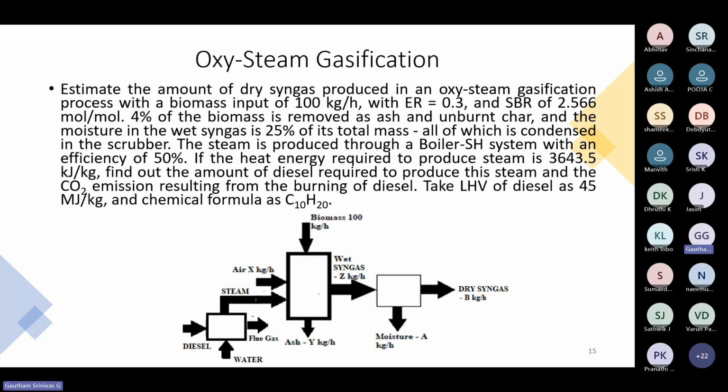So this is the heat contained within the steam. This is your energy output for this system. What is the energy input? You have the diesel, 45 megajoule per kg times how many kgs here. That's what you need to find out. You do it in the same way that we did for the diesel generator before. Use the same method here.